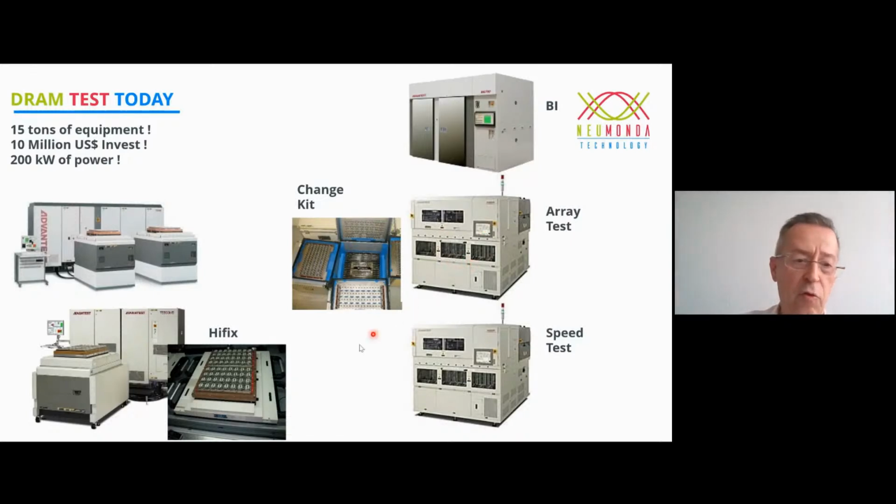After this, you go to speed testing. This is a typical speed tester. They're very expensive, so frequently only with a single test head. Handler again. Then you do speed testing. Is your memory circuit working at speed? For highest quality, you also do it at 2 temperatures, high temperature and low temperature. So 5 test insertions before your DRAM is finished.